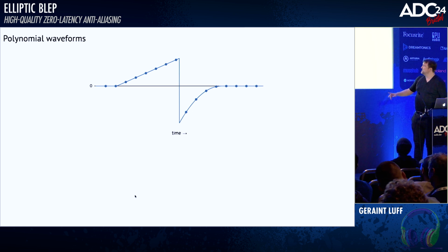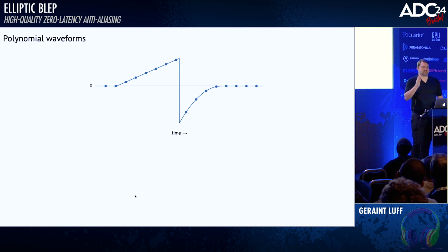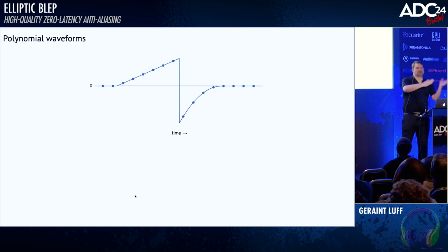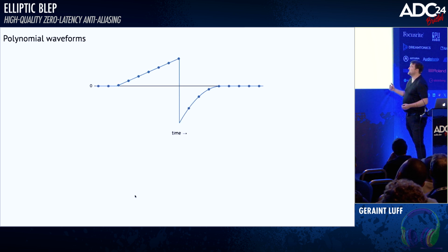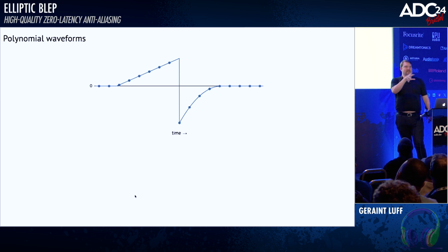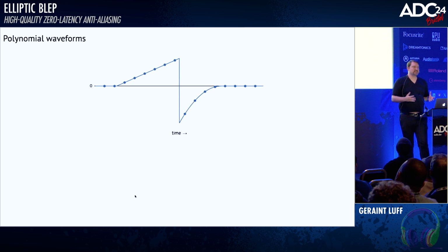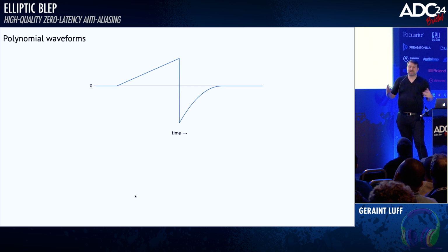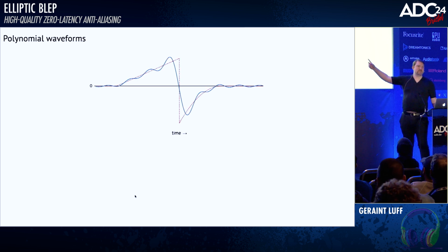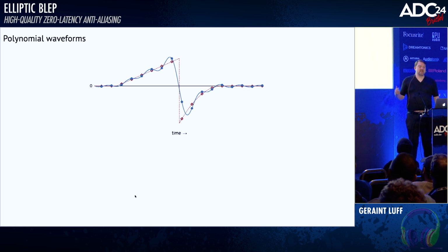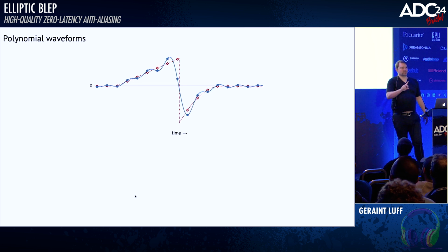The problem is, this is very sensitive to exactly where the samples land in the curve. For different sample positions, it can land one side or the other of this discontinuity, and it's not very good. And actually, as you've got things that line up differently over time, you get inconsistencies, and that's one perspective on where aliasing comes from. Now, ideally, the thing we want to do is to get a band-limited version of this waveform. So we get this and we apply some perfect low pass to it, and then we sample that low-pass version, which, as you can see here, doesn't have this issue where crossing the boundary gives you really fragile and inconsistent behavior.